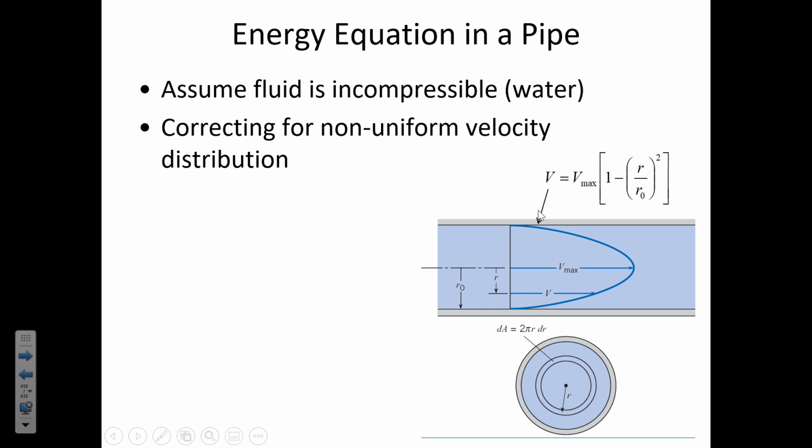And you get a little bit further from the pipe, and then there are some molecules that are able to move at some positive velocity. But the molecules that are in direct contact with the stationary pipe material, because of viscosity, because of friction of the pipe, those molecules can't slip over the surface. And so this velocity profile is related to the shear stress that is applied by the material to the fluid, and also it's a function of the internal resistance of the fluid, which is to say the viscosity.